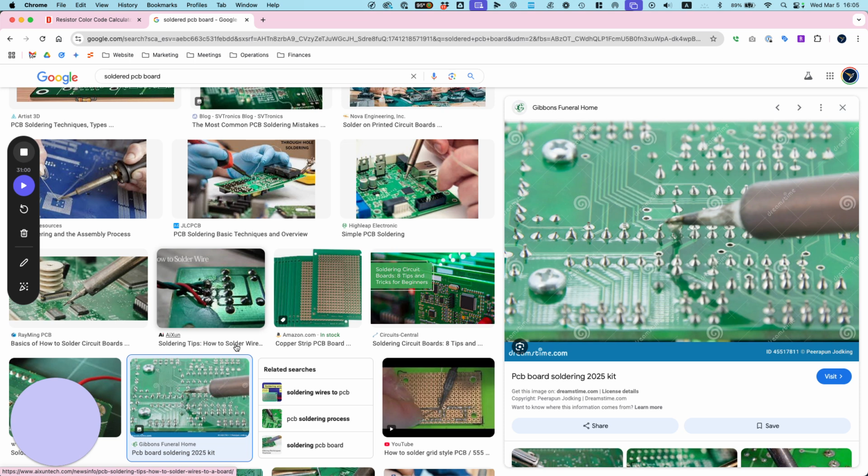Okay, so I just trimmed it, and now I'm going to lay it across like this. All right. This is going to be my poor man's way to do it. Can you hold this because I don't have a helping hand. I'll hold it from this side. You're just going to solder on top of it? Yeah, I'm going to solder right there. Hold it down, right there. There's one of the legs over. I just brought the leg over, so I'm going to heat up this joint right here.